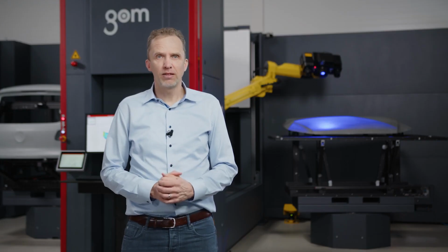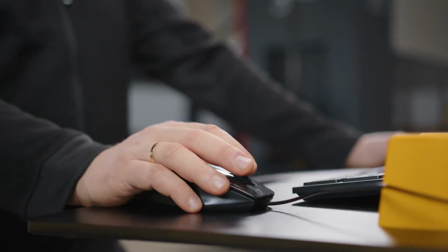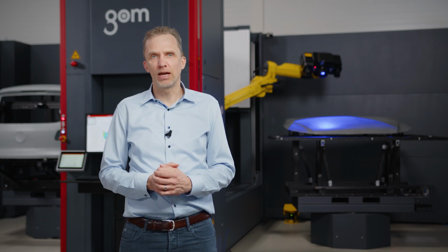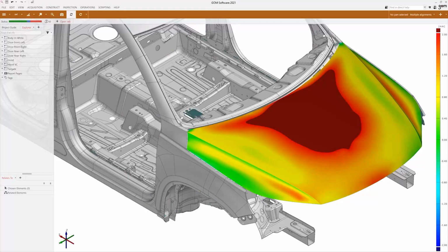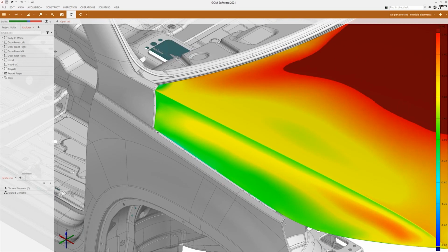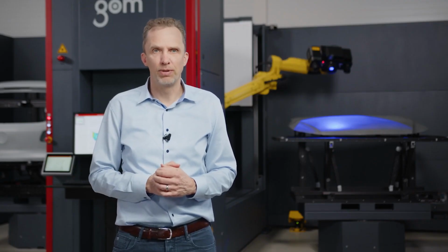The special thing about the evaluation of the front hoods is that the alignment of the measurement data to the CAD model is done by the outer shell of the hood only. This is because it is wanted to simulate the later assembly situation where the flush and gap to the fender, for example, define the visual impression of the part.